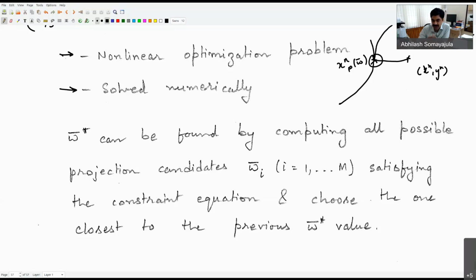But the same process of our LOS guidance scheme still works. We only have to identify the location of our path tangential frame and then apply our LOS guidance scheme to figure out our desired course angle. So the approach still works for curved paths as well, but the only challenge is to find out where the path tangential frame's origin is at any particular time.